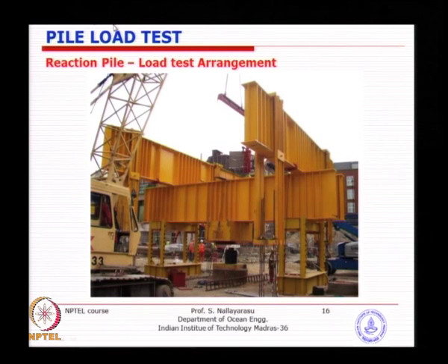Typical reaction pile setup. So, you can see here this is the pile being tested, the pile that requires to be tested, and you have the jack being placed here, and these are the pile heads. On the left side and right side you see the pile heads, which the piles already have been driven with, and when you push this hydraulic jack upwards, the reaction is applied to the test pile, and the reaction piles on the left side and right side should have sufficient capacity, and basically that should be designed.